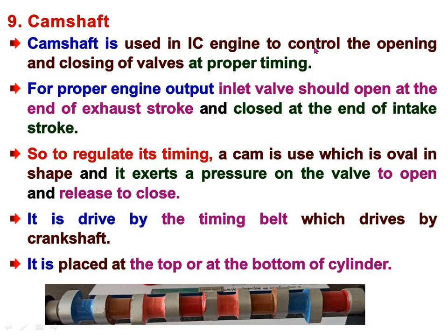So the camshaft is used in the engine to control the opening and closing of the valves at the proper time. It means at the proper time, the inlet valve must remain open, and at the proper time, it should be closed. At the exhaust stroke, to expel the burned gases from the cylinder, the exhaust valve must be open, and when the exhaust stroke is completed, the exhaust valve must be closed. This opening and closing of the valves is done by the rotation of the camshaft with suitable timing.